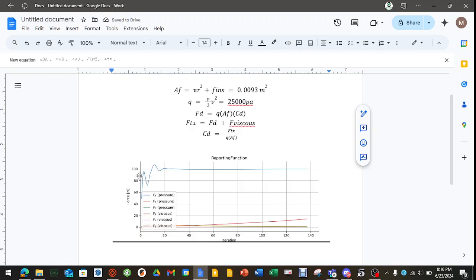And so in Ondsel with the CFD workbench, we can get all of these plots. You can see the force in X, which is right here, and then the viscous, which is right here. We add those up, and that's what becomes FTX. So I want to show you how to do all of that.